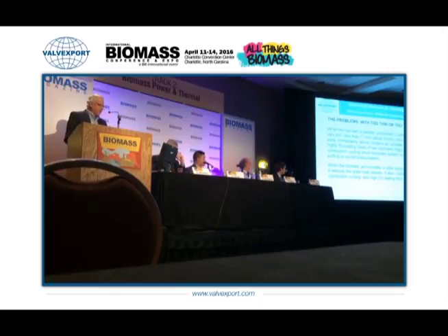When the biomass accumulates in piles above 6 inches, it reduces the grate heat release, meaning that what you calculated as the average heat release is not going to happen. It also creates combustion cycling and high CO exiting the furnace.